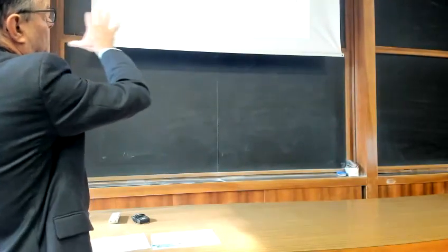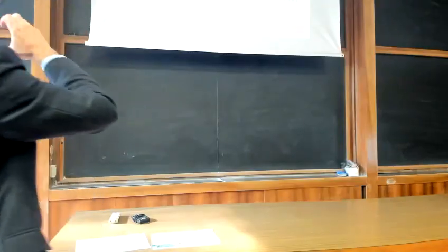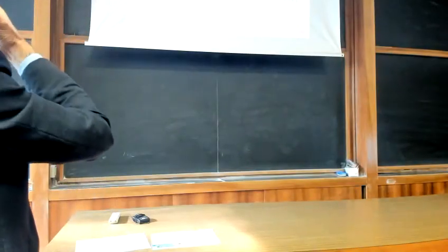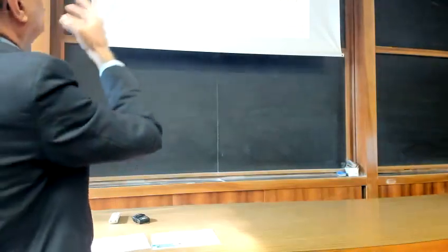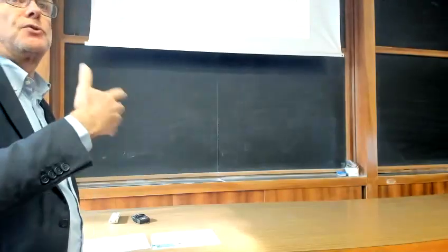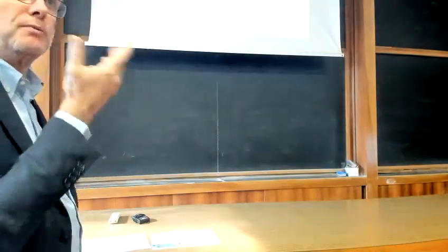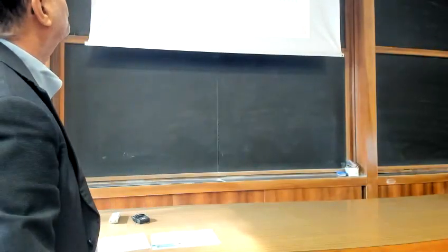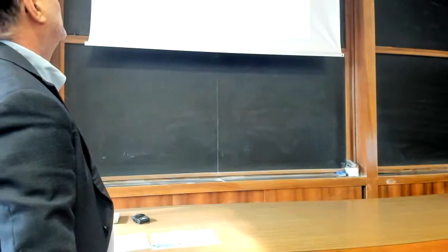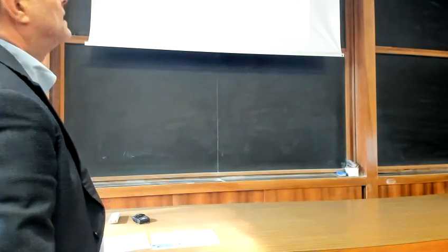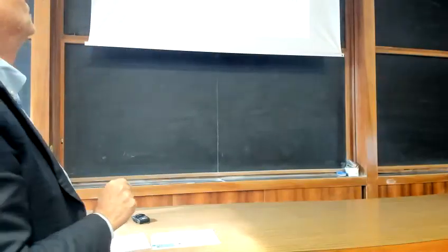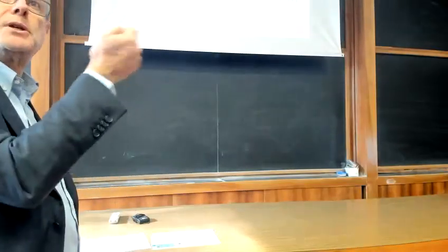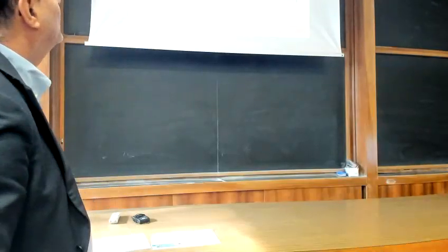and this plot provides you with the value of N gamma as obtained by several methods for a phi equal to 30. 30 is a much more common possible value. It's not as great as 44 as before. So this typical common value, phi equal to 30. Delta is the angle of friction between the footing and the soil below, which in this case was assumed equal to the angle phi.